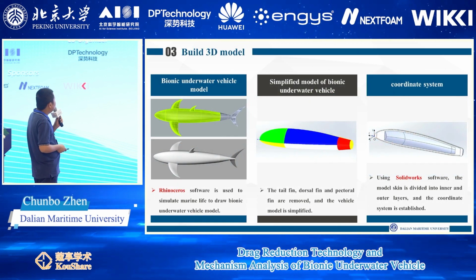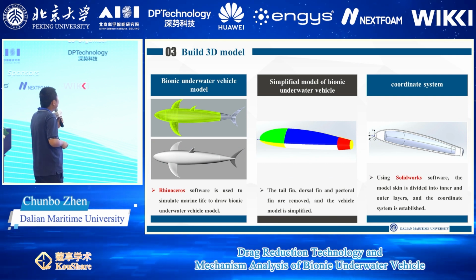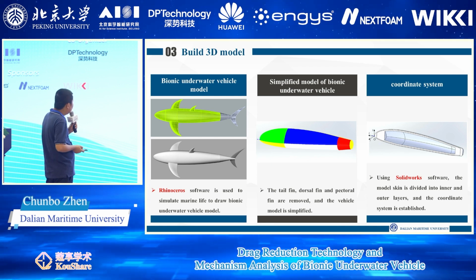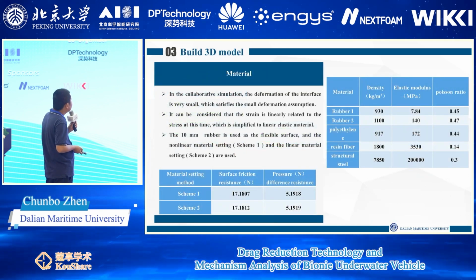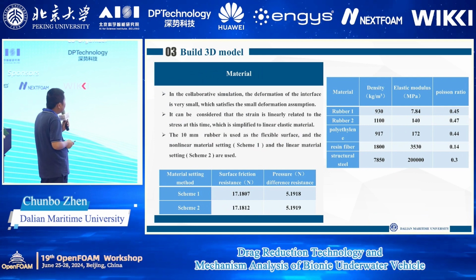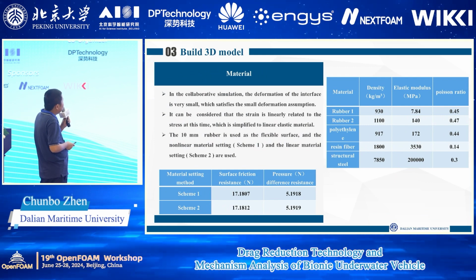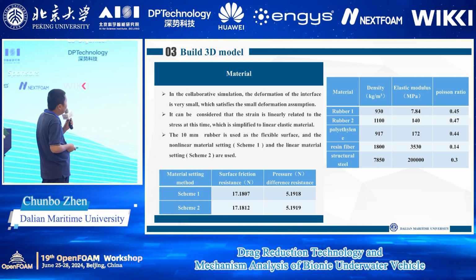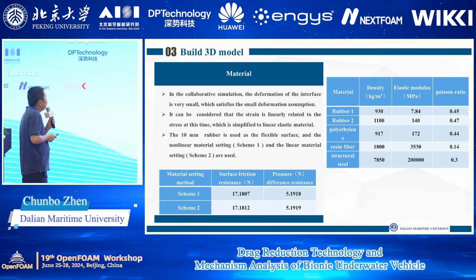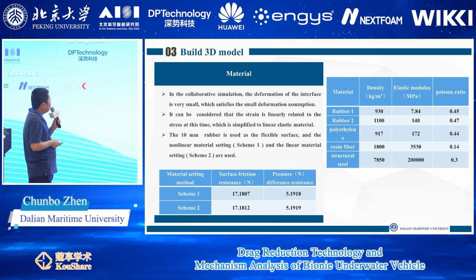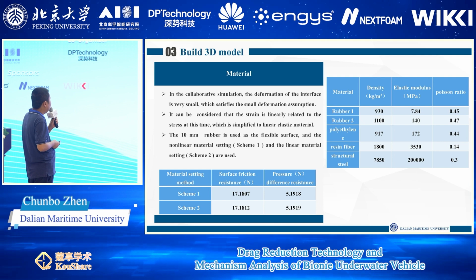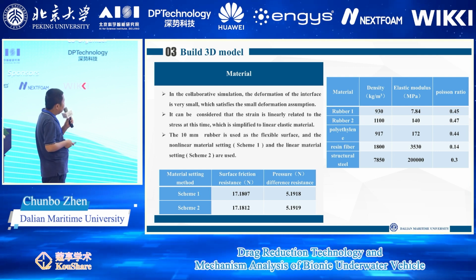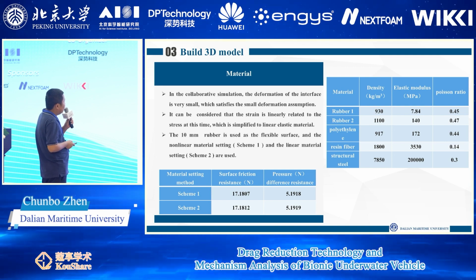This is the three-dimensional model for the underwater vehicle and the coordinate system. In the collaborative simulation, the deformation of the interface is very small, which satisfies the small deformation assumption. It can be considered that the strain is linearly related to the stress at this time, which is simplified to a linear elastic material.